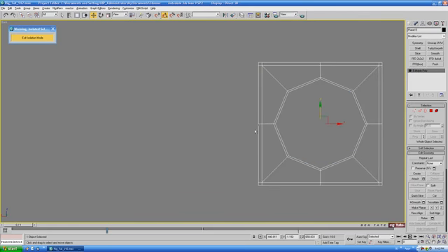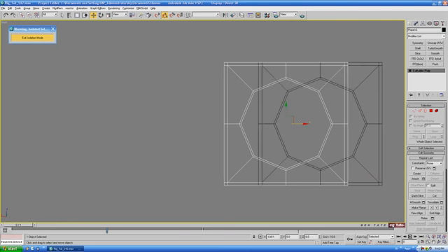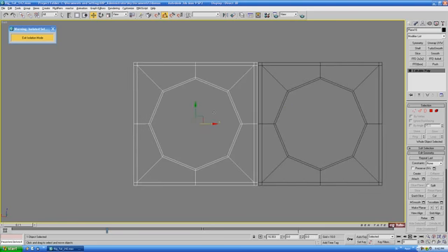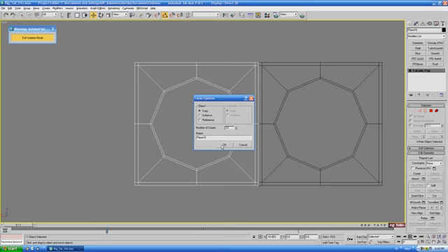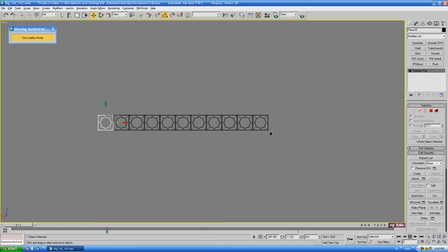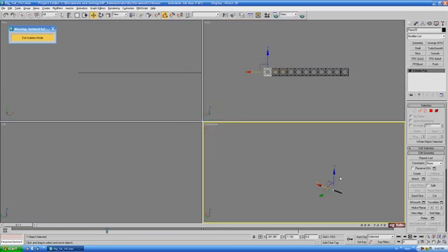and we're going to make some copies of this. So I'm just going to hold down shift and drag it over on the X. Okay, we'll line up the right edge of this piece with the left edge of the original right on top of each other. And let's choose copy here, and we want to do, say, 10 of these, and okay. Okay, I think that should probably be long enough.